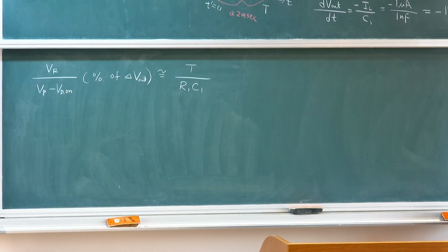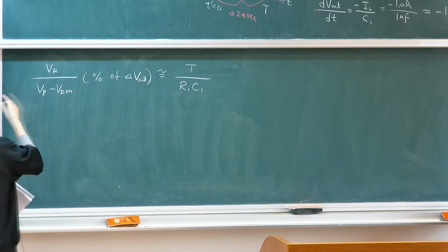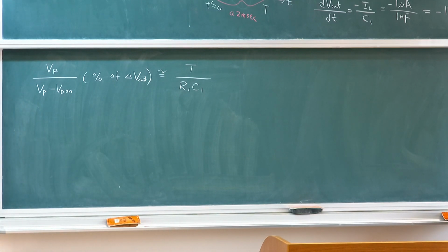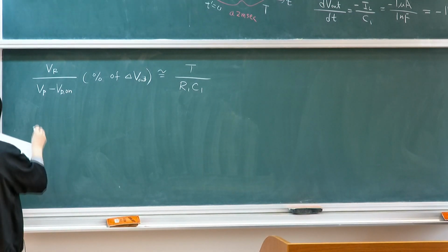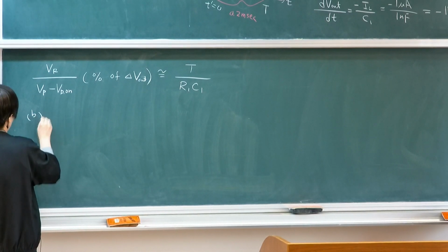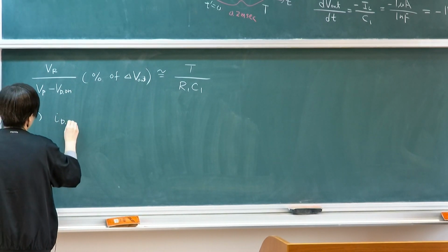So the second part is then, you get the slope and then you can get the projection and find out the ripple voltage. And this is of course approximated, assuming that there's very little difference because it's very close to the peak. So you can still use the same approximation as we did for a resistive load case. And then for part B, what is ID maximum?